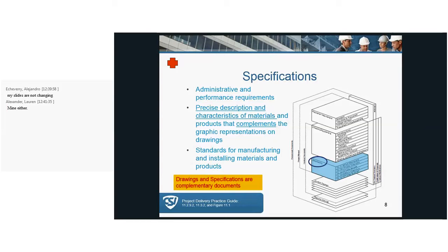And then on top of that, you put in a performance requirement that states it would be able to withstand a 50-pound wind load. And maybe your mullions are spaced such that they cannot resist that sort of wind load. So this is an example of over-specifying, and you need to be aware of what needs to be avoided.